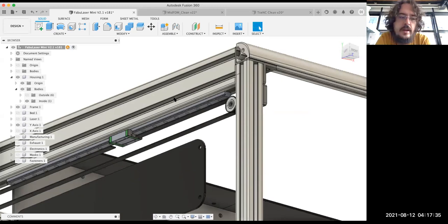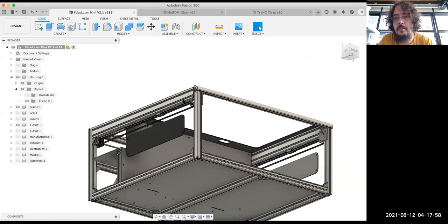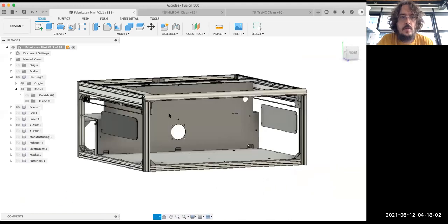So it's worth mentioning that I also created some fabricable linear guides that work very well, but they're made out of POM plastic. In this case, this stopped me from using these linear guides in this machine because of fire issues. Because POM is plastic, it can catch fire, so the more parts in metal here, the better. And also, it's very hard to make them as precise as these rails. So this is the y-axis.